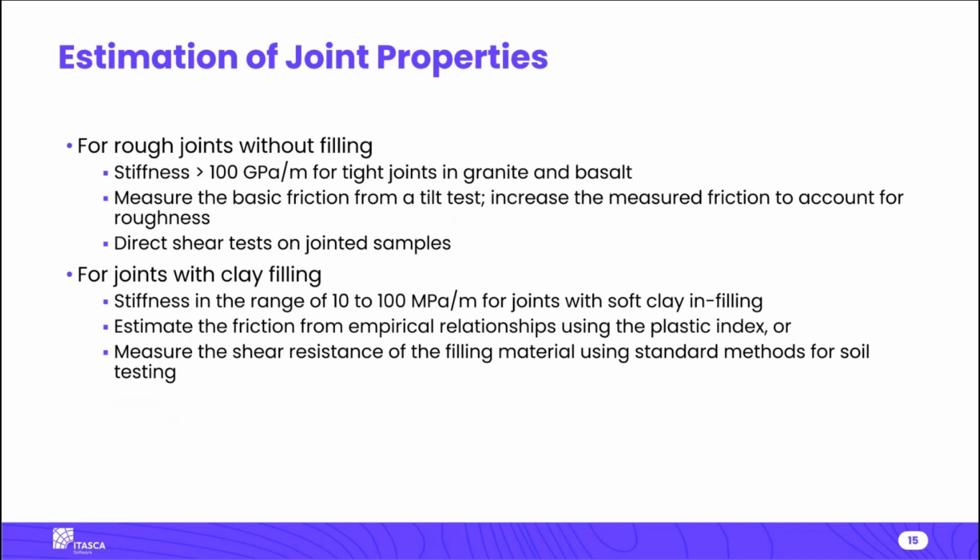Estimating the friction is usually a little bit easier. You probably have some intuitive idea of what the friction might be. Again, it sort of depends on how clean the joint is. Top case, you might have a higher friction. In the bottom case, you might have a lower friction. This is also possible to determine using lab studies of a joint surface. It's not that hard to figure out the friction.